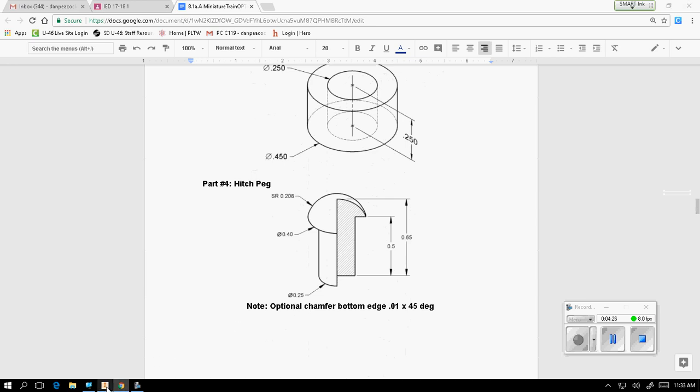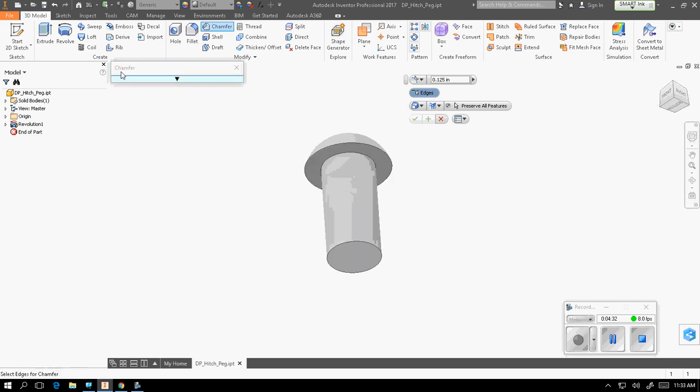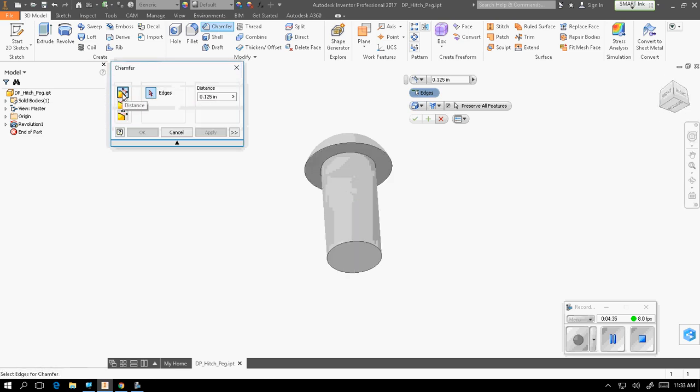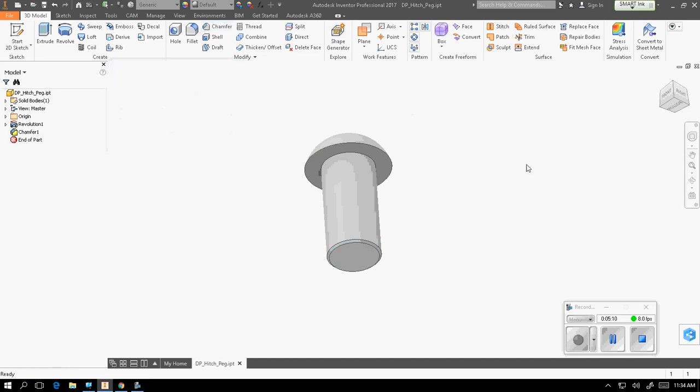we're just going to go back here, and we're going to select chamfer. The pop-down window has a distance and an angle, and 2 distances. We're going to go distance and an angle because it was 0.1 by 45 degrees. So this asks the face. We want to click this face. It asks the edge. We want to click that edge. We want the distance to be 0.1, and we want the angle to be, I think it was 0.01. Hang on a second. Yeah, 0.01, and it's already at 45-degree angle. And that gives us a nice chamfer in the bottom of that.